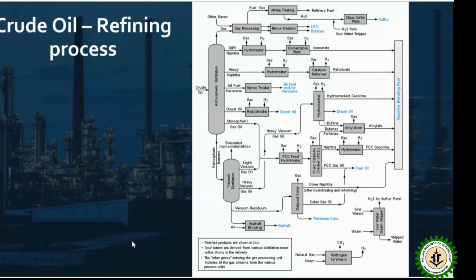oil refining process used to heat up the entire thing by fuel wood. They used to burn woods to get a temperature. But the problem with wood, first, is the removal of ash, which has to be very quick. Second is the required amount of temperature. For coal, the GCV is much higher than wood, because woods have moisture inside them. So with the lower GCV, you cannot reach a higher temperature.